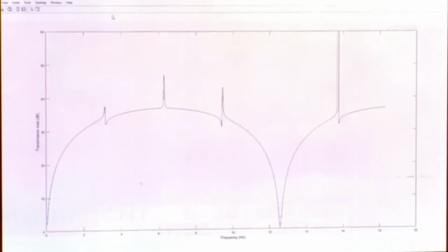What do we see here? If we go to the cursor and put our mouse here, we get the peak almost at 3.14, k naught L is equal to pi. That might just be because of frequency scaling. So, we are able to almost kill the trough that would have occurred at k naught L is equal to pi if the extension was not equal to L by 2. Similarly, because the extension at the outlet is L by 4, we are able to kill the second trough, which occurs at 2 pi, that is 6.28 or something like that.